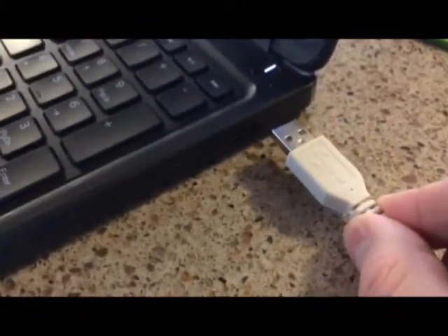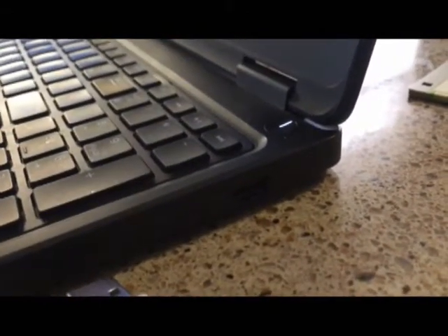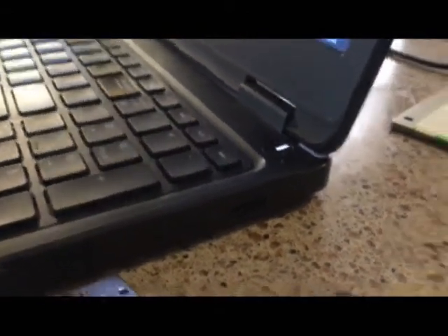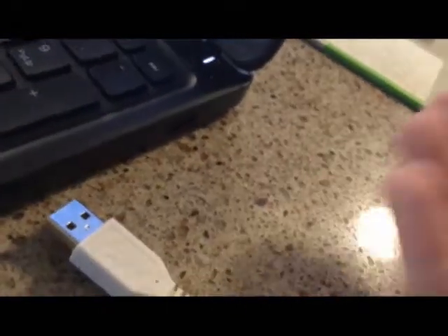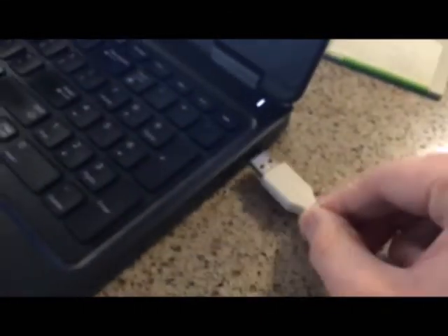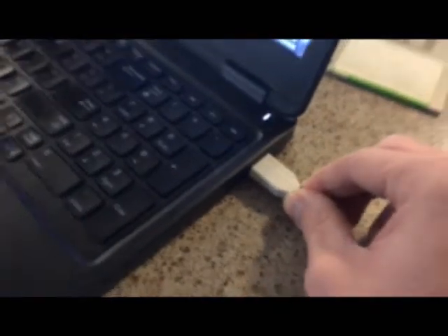And so what I mean by this is that the port that the Kryoflux plugs into from the printer cable must be something that is on the motherboard of your computer. It can't go into like an extension or something, or maybe you have a dongle that plugs in that gives you extra USB ports. You cannot plug this printer cable into that because it somehow affects the timing of the